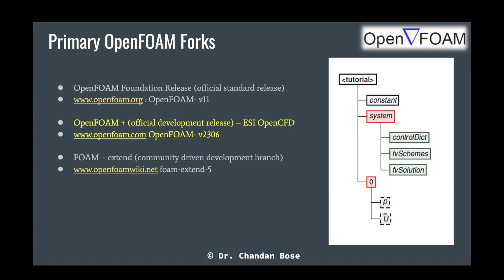So we first run the simulation with RANS or URANS solvers and let the flow go to a developed state. And then we take the solution and map it to another case folder and basically initialize another simulation with that result of the fully developed RANS flow, and then start DES or LES or higher order turbulence simulations, for gaining stability to reduce the effect of the transients.